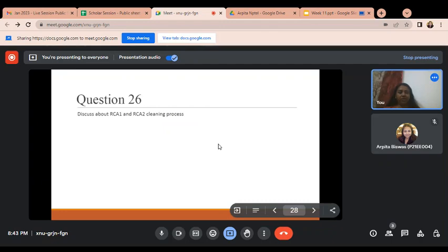contamination from the wafer. So RCA1 is prepared by a mixture of some chemicals like NH4OH, H2O2 and DI water, and the ratio is DI water 5, H2O2 1, and NH4OH 1. So DI water, H2O2 and NH4OH is 5:1:1. Using this mixture of chemicals, we prepare RCA1. By using these chemicals, we can remove the organic contamination from the wafer.